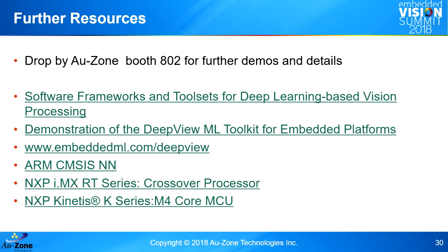So we have a model that will run across any of these devices. So we look at using 32-bit floats first, and then if we need to do further optimization, looking at integer math after that. So in this case, the performance was acceptable without going to the further optimization of integer math.